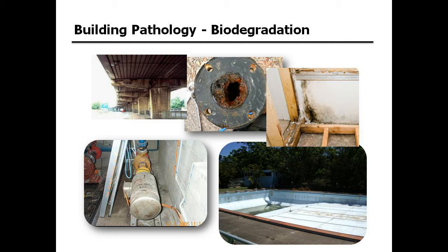Often with plant, equipment and buildings, it's advisable to have random spot sampling or random audits of more detail to look at components and how they're actually responding, behaving, and whether it's the right maintenance level.